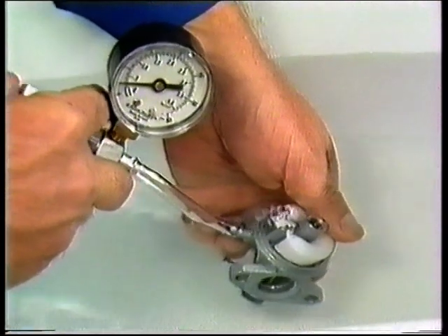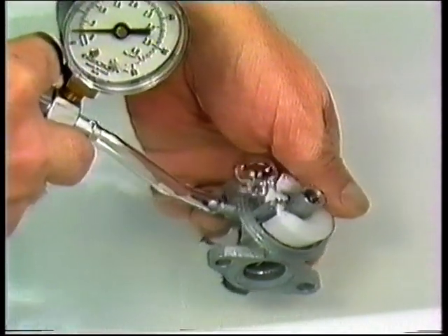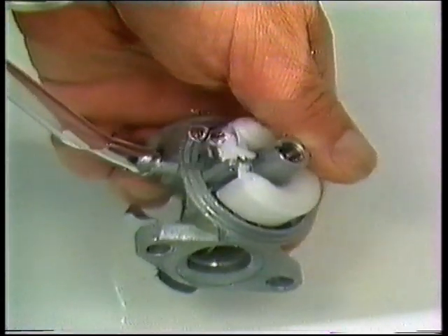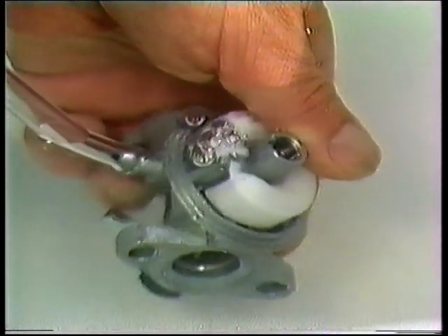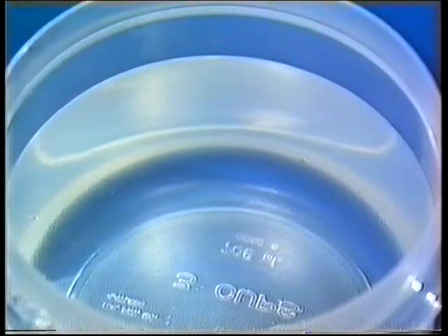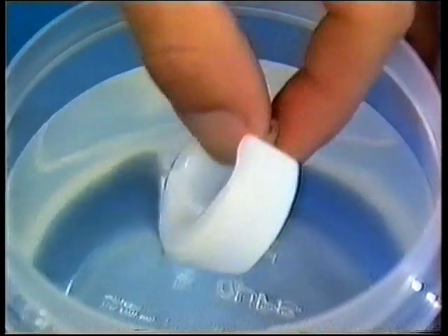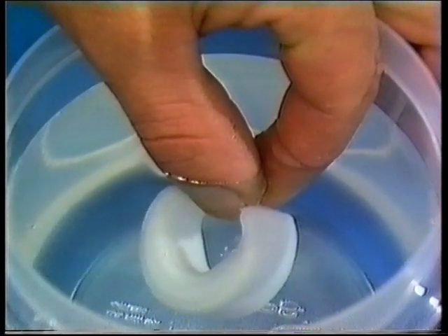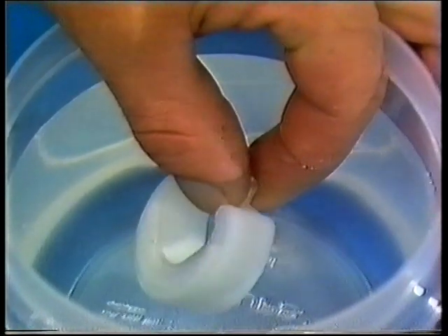Now, pressurize the inlet needle to 8 psi. If bubbles erupt from the casting or the inlet needle and seat area, there is porosity in the carburetor. If the component parts did not show any bubbles, check the float by immersing it carefully in warm water. Watch for bubbles around the seam. Another method that has been used to successfully test for static leaks is done with a simple 2-quart freestanding tank.